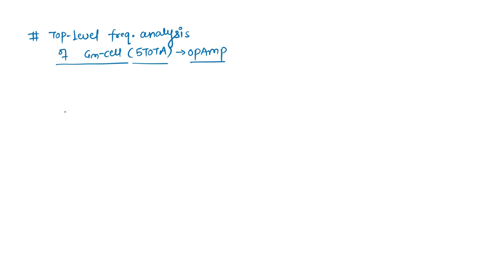So what we have seen is the open loop transfer function, where it takes the input and generates a current, and this current is integrated by using this load capacitance. Apart from this load capacitance, this GM cell has some output conductance or output impedance, which I call R0, and with this your gain is finite. Next, we'll see this in the closed loop response, then calculate the poles and zeros and whatever possible DC gain in the closed loop system.